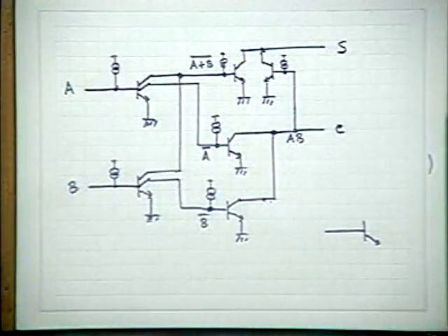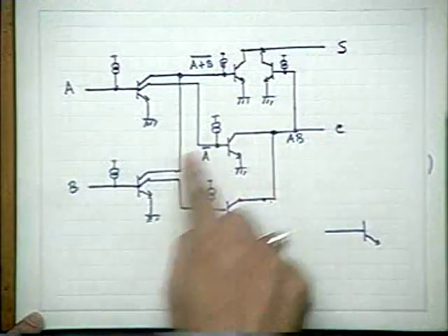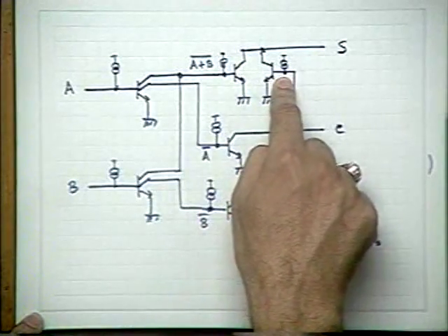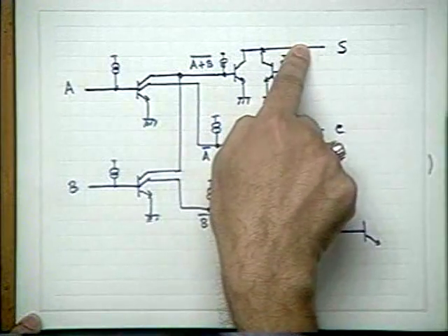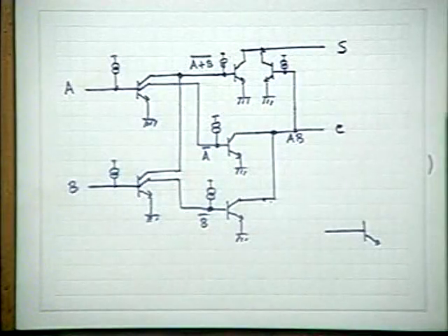They are distributed. So you have to provide that injector current, and you have seen how easily it can be done. Just place an injector rail, and on either side you place the bases. The problem is solved. Therefore, all these things really do not occupy much space. Though effectively there are a large number of transistors, all these PNP transistors, whatever have been shown here, they are achieved through a very simplistic, very tricky way of realizing them using a MOS transistor concept. So let us now see how this can be realized on the chip.